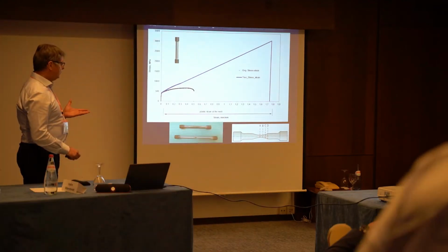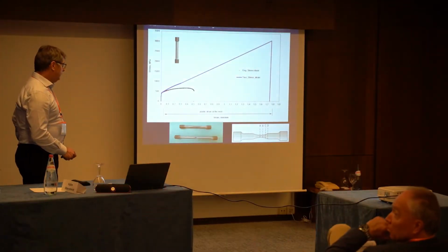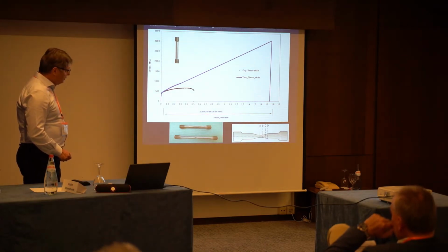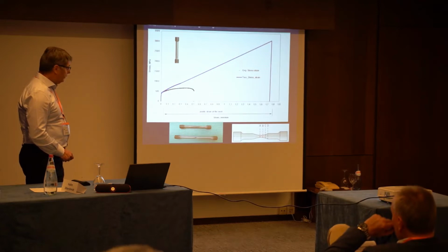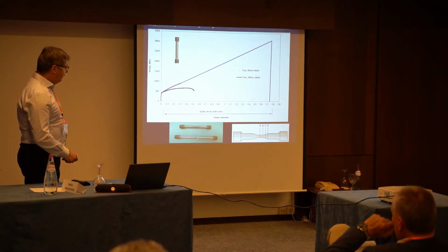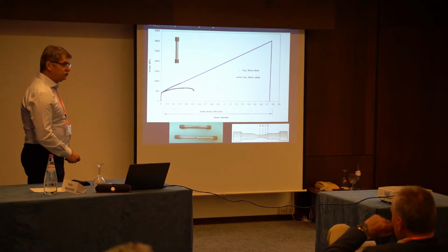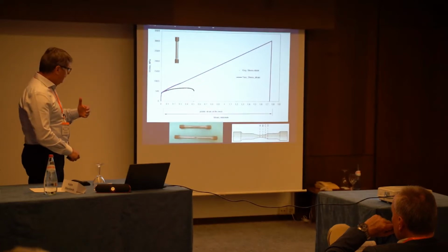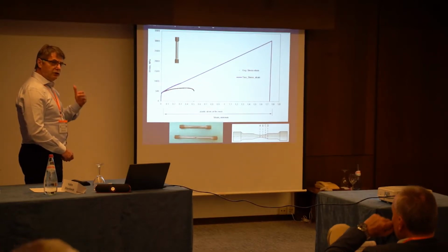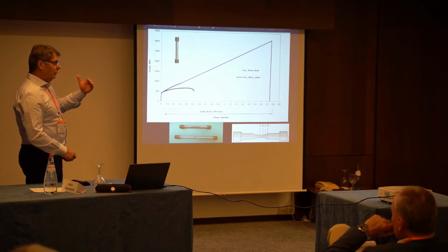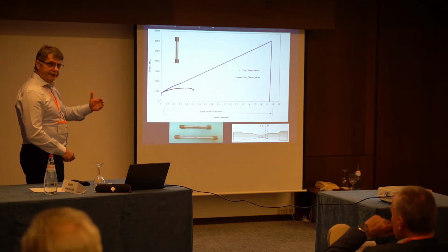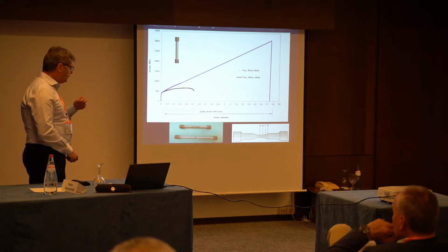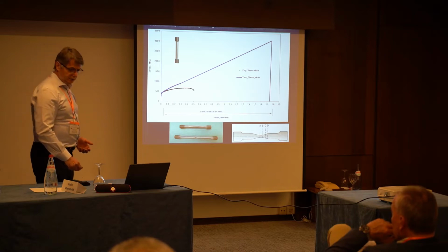We want to see what happens during the tensile test. During the tensile test, you have transformation to martensite. The highest transformation to martensite you have in the middle. It's a narrower spot because the transformation is higher, and lower in point D, this section D. We cut this specimen, which is completely unbroken, in order to determine the concentration of martensite and to follow the correlation with the hardness, because the change of properties from austenite to martensite also changes the hardness of the structure.